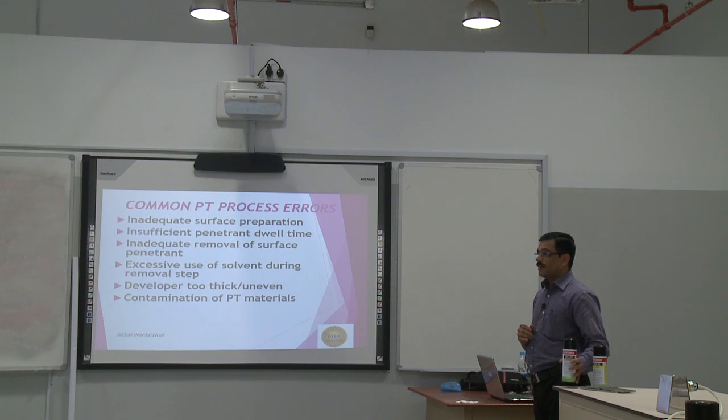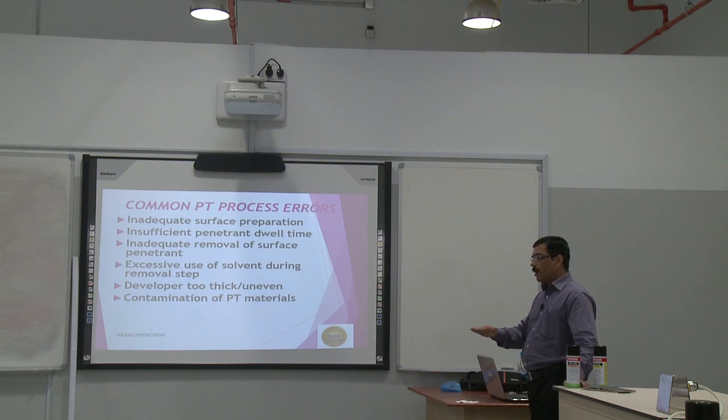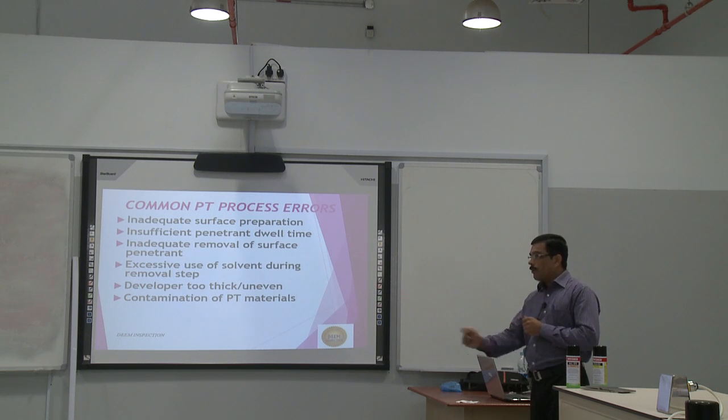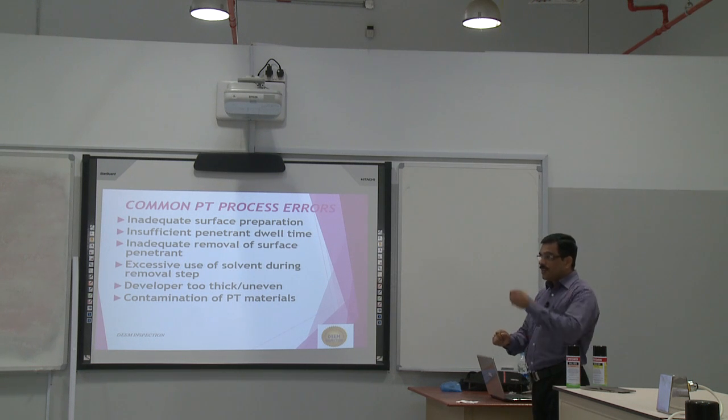You are cleaning only this developer. If you leave the developer on for 10, 15 or 20 minutes, the developer has the absorbing capacity. It will absorb all the chemicals. You wipe it out and apply the developer again. Again you clean the developer, and try to apply the developer again. If there is any penetrant still inside, it will come out.